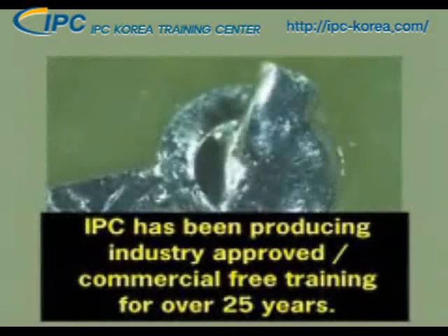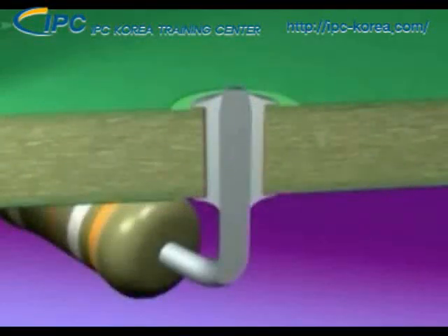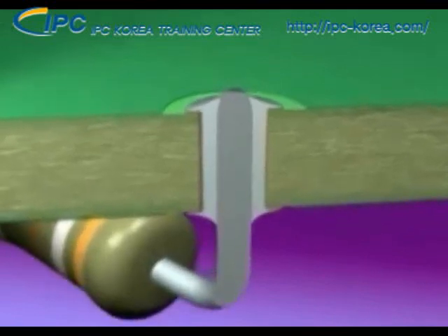Another rejectable condition is when the solder clumps on the surface of the connection. Notice there is no feathered edge apparent and the contact angle is irregular. Our last parameter for the solder side is lead visibility.